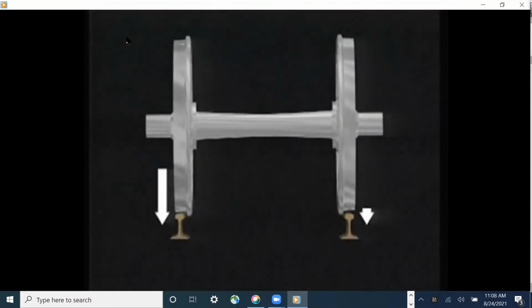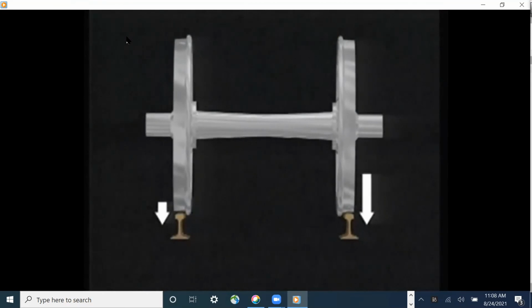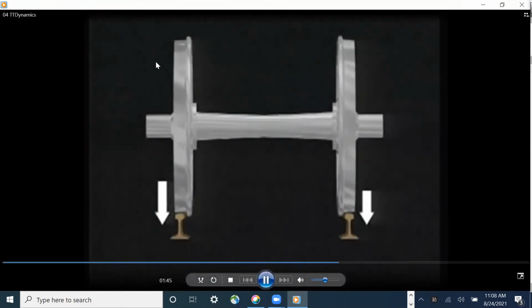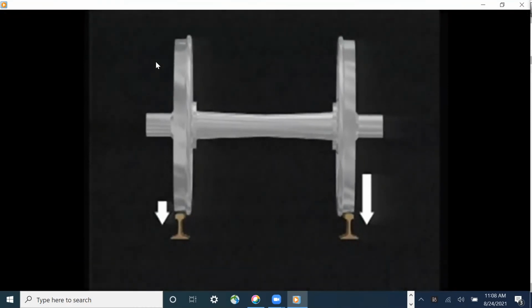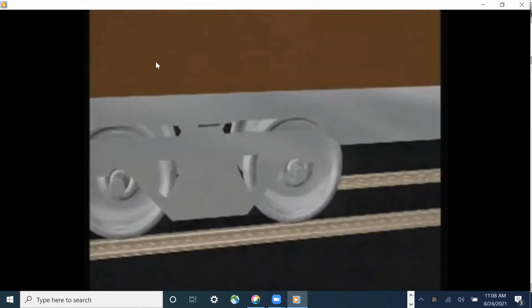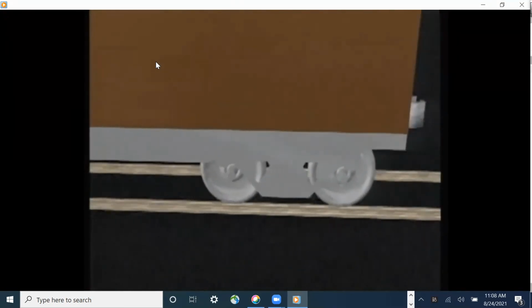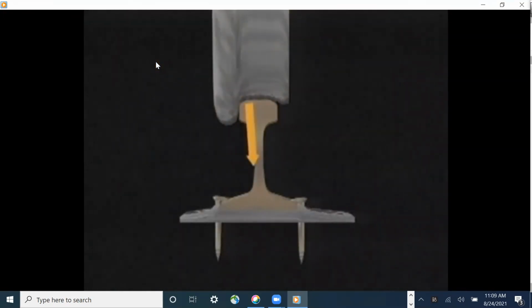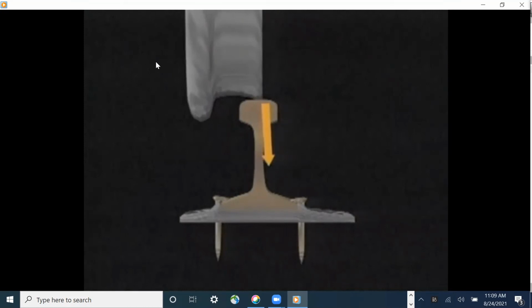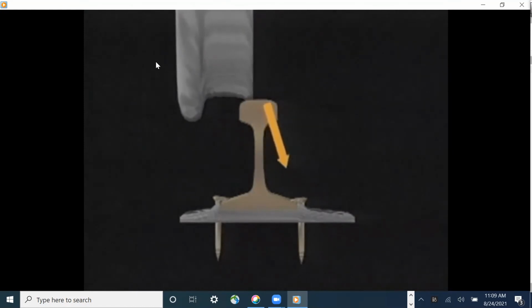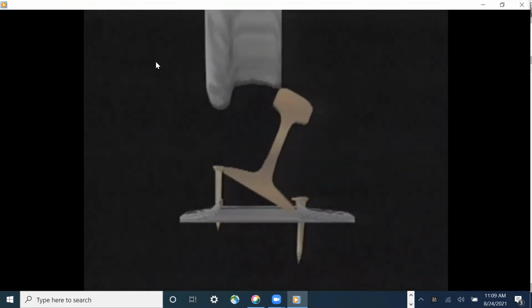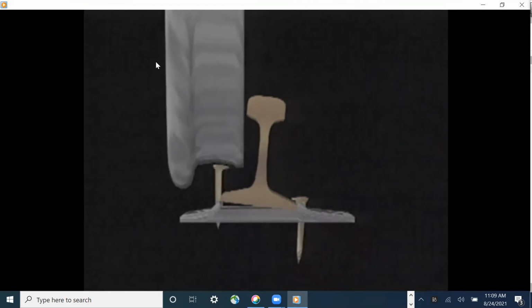When considering vertical forces, remember that any time the load of one wheel decreases, its share of the axle load may be transferred to the opposite wheel of the set, to the other wheel set, or to the other truck assembly. If the increased vertical load is not properly centered on the rail head, low rail wear increases, as does the probability of the low rail tipping, allowing the wheel to drop inside the low rail.